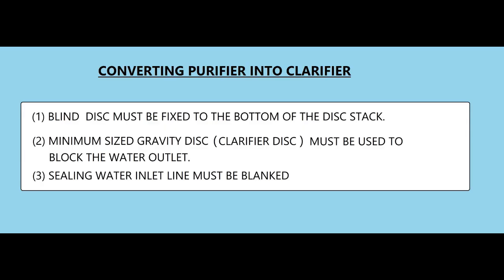Converting purifier into clarifier. Blind disc must be fixed to the bottom of the disc stack. Minimum sized gravity disc, that is clarifier disc, must be used to block the water outlet. Sealing water inlet line must be blanked.